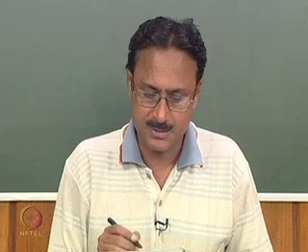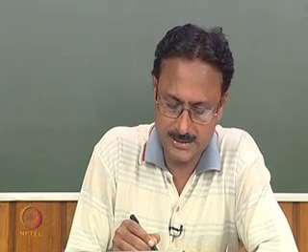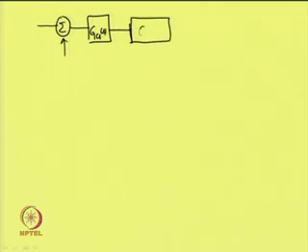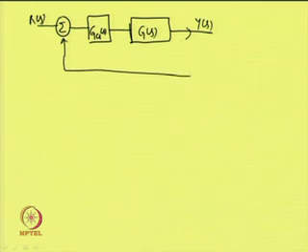Now, we shall design a PI/PD controller, which in block diagram form can be given as a PI controller having GC1(s) and the process dynamics given by G(s), output denoted by Y(s) and reference input by R(s), and we have the feedback path, a negative feedback over here.